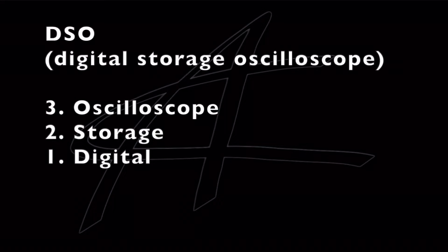So digital storage oscilloscope, this is what it boils down to for me. You have 3 factors here, working down from 3 to 1: oscilloscope, we know that, 2, storage, and number 1, digital. As far as the digital oscilloscope part, I can take it or leave it. I'm fine with the analog stuff until you get up to super high bandwidths. But the joy of digital scopes is the triggering tricks and the digital decoding and all of that kind of stuff. That's what I was talking about in the previous video, and I will talk more in the future about criteria for selecting a scope.